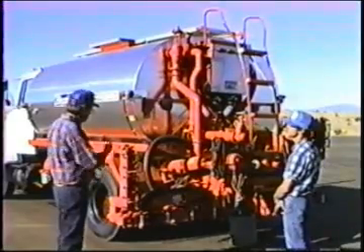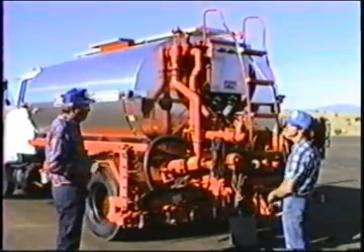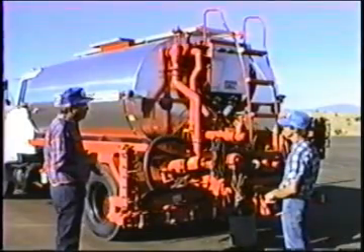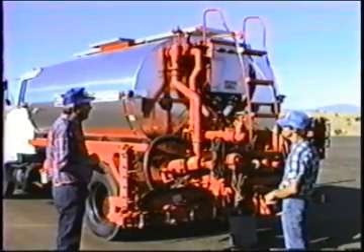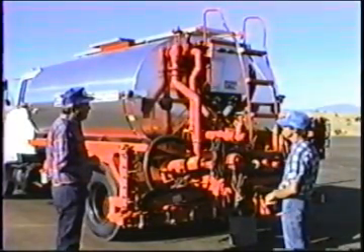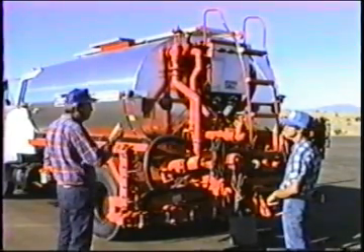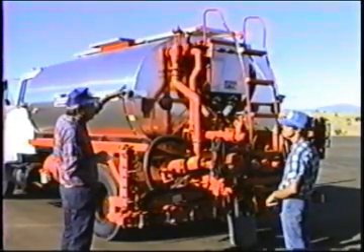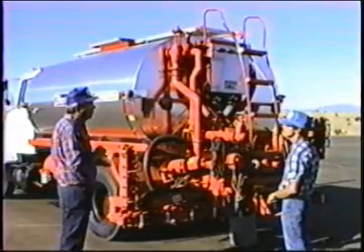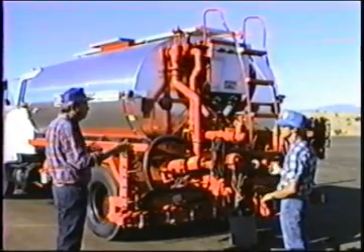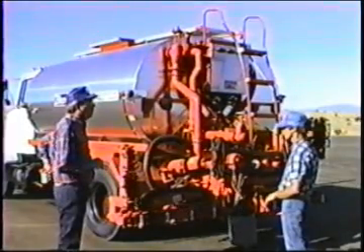That is, open up all the sections and back the thing over a ditch. Get the pump running in the forward direction, and last, open the tank valve. That is, now we've got the pump running, the spray bar is in the spread condition so that the bypass valve is closed. Okay, now if we turn the asphalt into the pump, it's going to go into the spray bar and push it right directly onto the ground.